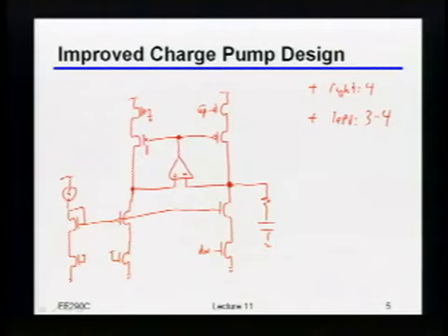Well, you have to be a little bit careful, because if it's not up to the bandwidth of the loop, you might start introducing some pole-zero doublets and things like that. So it might still be okay, but generally speaking, it doesn't cost you that much to get the bandwidth there, so you'll basically just do it, to make sure that it's behaving the way you'd like it to.